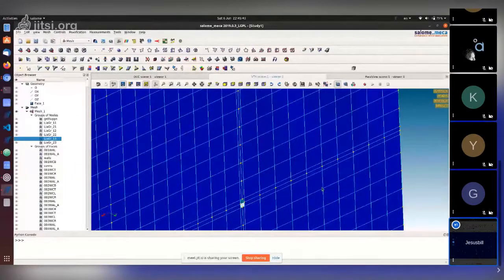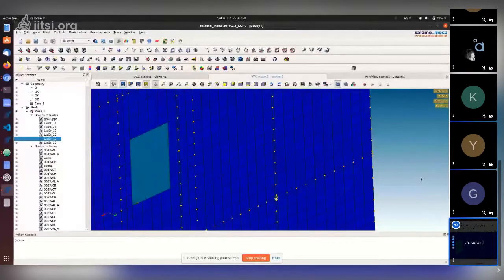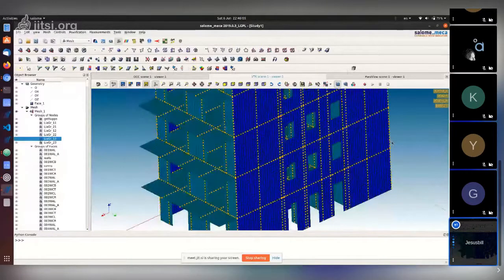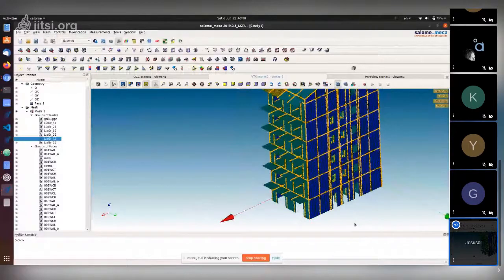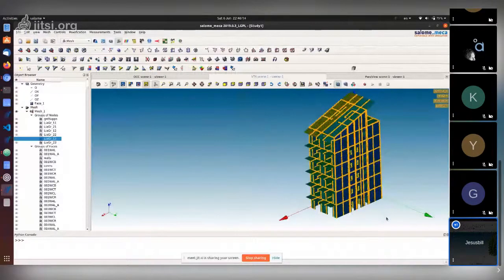In Code_Aster, you can also not have coincident nodes, and then tell it to bind these edges together. But this is another command that can be heavier. Usually this is how I work, but it can depend on how anybody operates. Thank you. Yeah, understood. You're welcome.